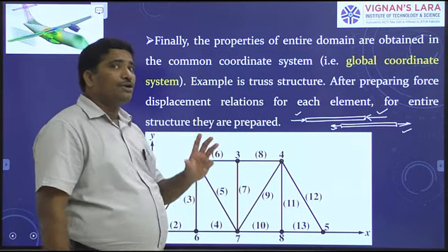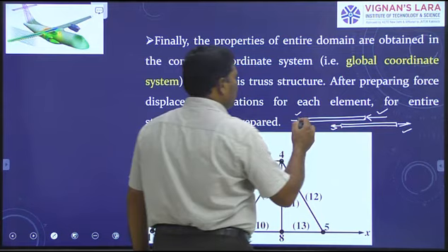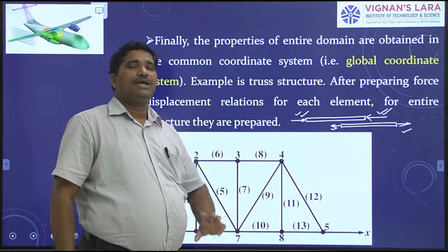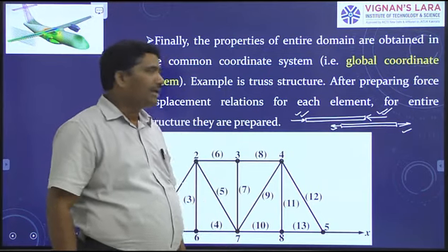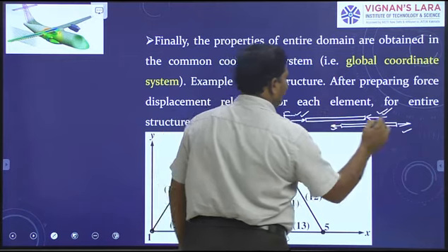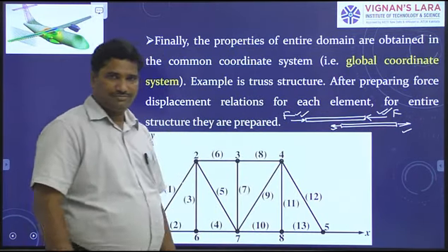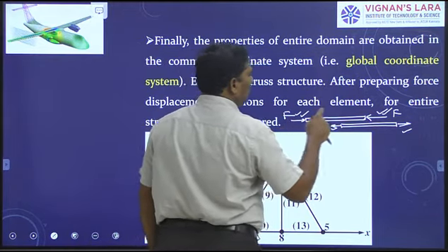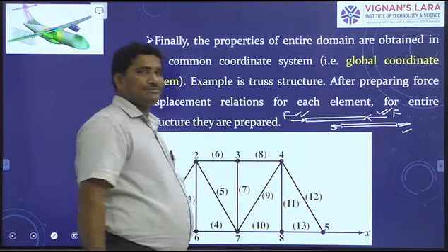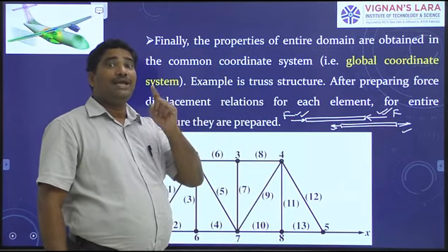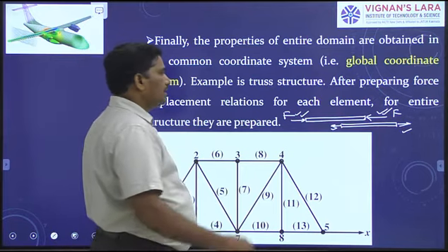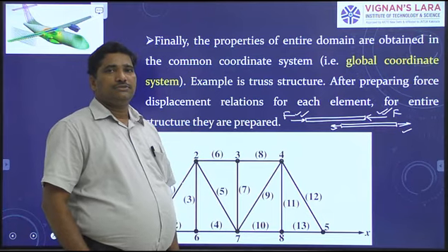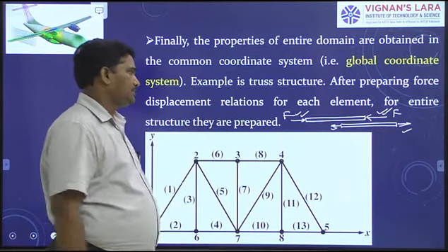A truss member does not undergo bending because the forces are collinear in action. They do not constitute any moment. Why? Their magnitudes are also the same. Right? A truss member is subjected to two equal and opposite forces. They are collinear in action. Hence, the truss member is not subjected to bending. Either compression or tension takes place.